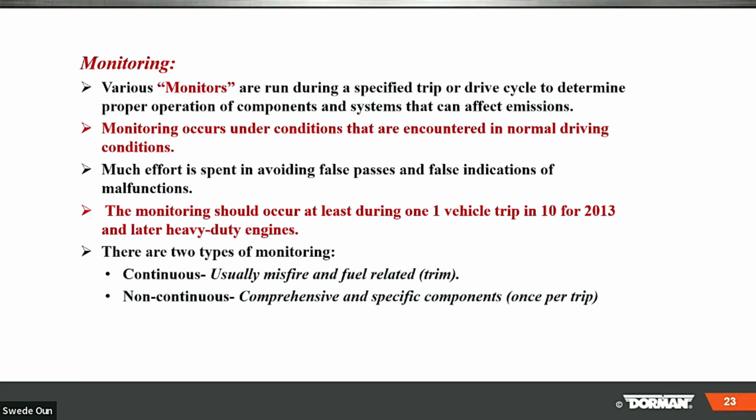Because if it runs those monitors and you don't have a check engine light come on, and everything's run, you know what? Pat yourself on the shoulder. You did a good job. Documented. And this way, if the vehicle comes back in a week, 2 weeks, or 1 month, you can say: wait a minute, the computer actually verified that I did the proper fix.